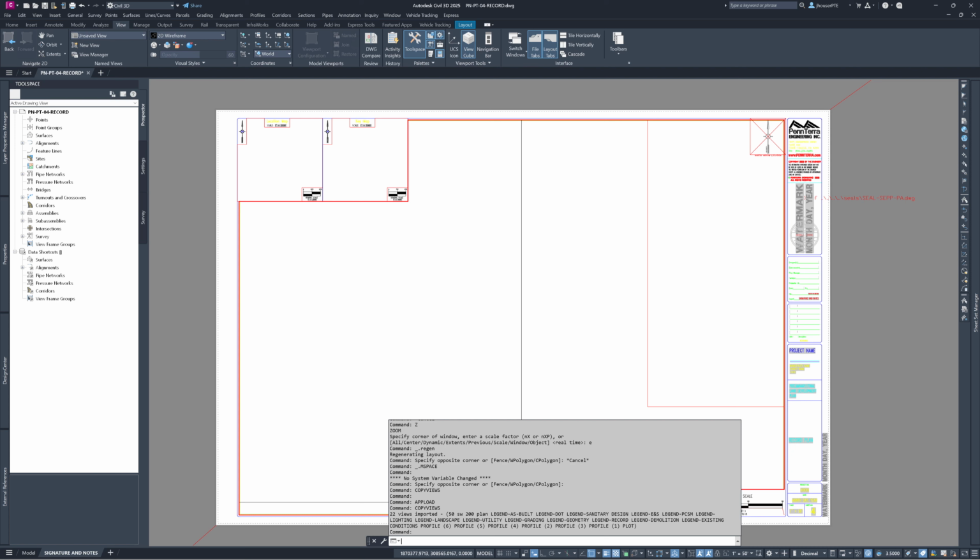So actually, let's first try. Oops. Also, if you can't get to your viewport, if you do Control R, and just continue, hold down Control, tap on R, it will toggle through the different viewports until you come to the one that you want active. All right, so here's my viewport where I would normally have my legend. So I have that active. It is unlocked, very key.